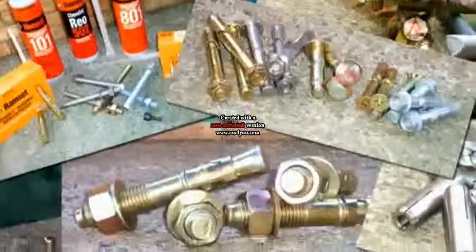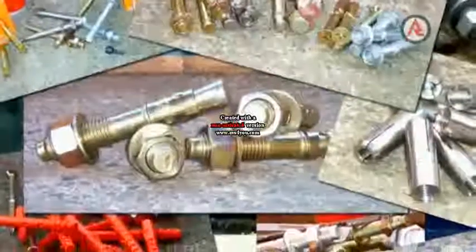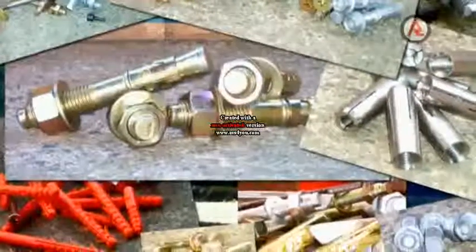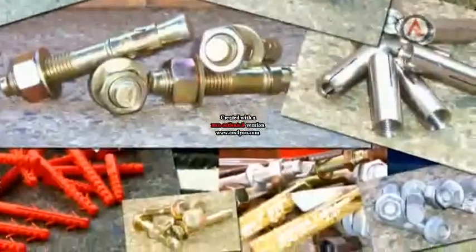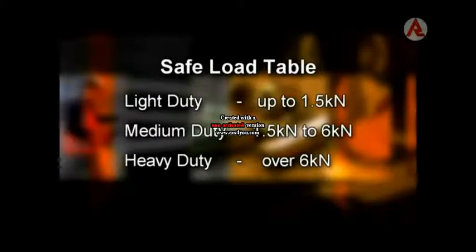Ramset masonry anchors are available to cover almost every anchoring problem. To choose the particular anchor suitable for any specific task, a simple selection sequence should be followed. First step is to determine the load which the anchor will be required to hold. Once the general load requirement is determined, next decide the environmental conditions.